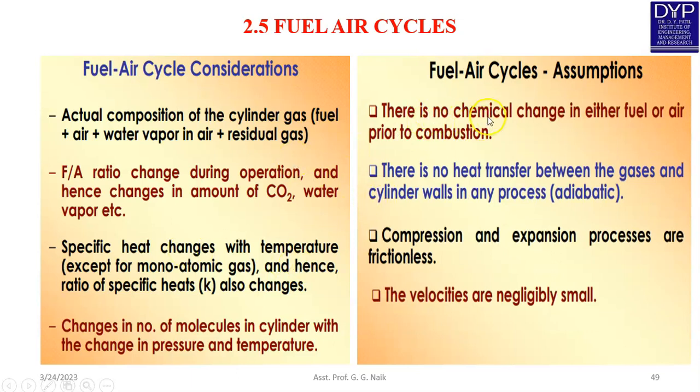Next assumption, there is no chemical change in either fuel or air prior to combustion. Okay, so here also we are assuming that there is no chemical change in the fuel or air prior to the combustion. There is no heat transfer between the gases and the cylinder walls in any process. Okay, that is adiabatic. Compression and expansion processes are frictionless. Okay, this is also an assumption, and the velocities are negligibly small.